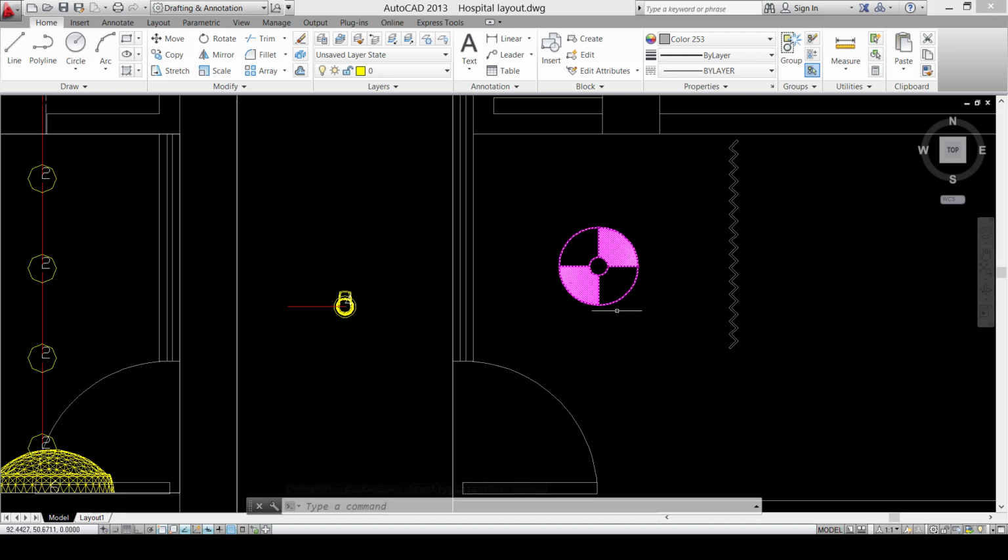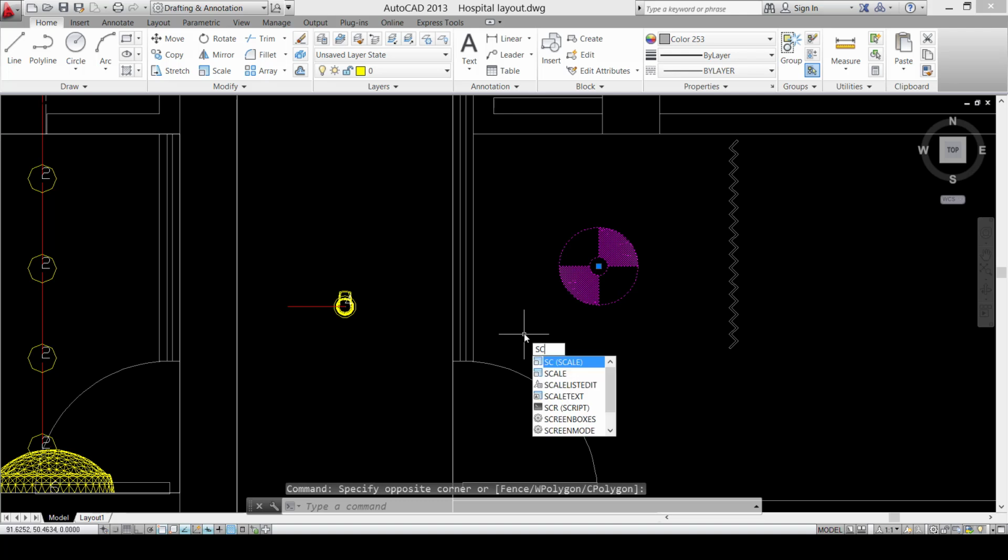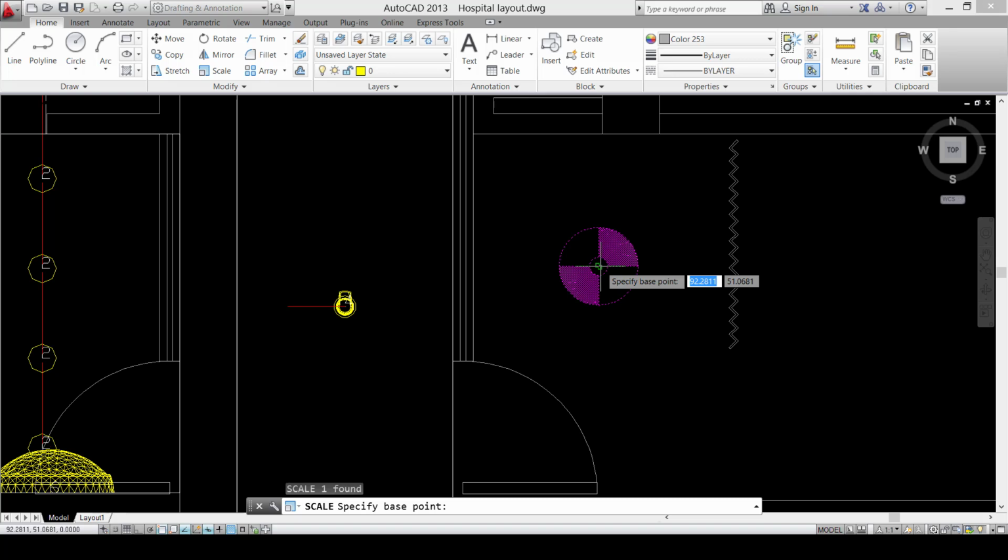So this is the sample of our new luminaire, which we will use to replace those spots. But the first important note here is that this luminaire's scale is much larger than this luminaire, so we need to rescale it. This is for the design to have a suitable scale for its different parts. So I'll select this luminaire and press SC and enter. This is to scale it. And now we specify the base point. And now we can make the scale factor 0.3, for example.